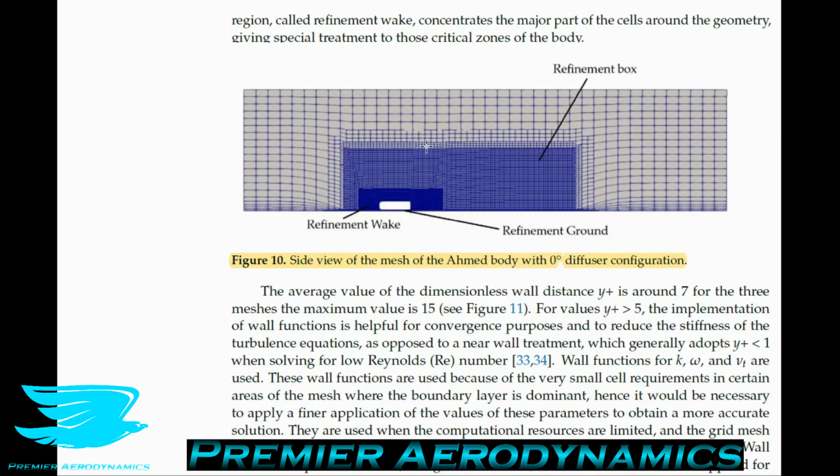Another thing to point out is that going between low resolution and high resolution regions, we have something like a boundary layer, well, I shouldn't say boundary layer because you might get confused with what I mean. It's not a boundary layer, it's a transitional zone between the coarser mesh and the finer mesh. This is just to help reduce discontinuities between these two zones, which could result in divergence in the CFD simulation. So it goes from very coarse to somewhat fine to a little bit finer, and then finally gets to the fine zone at this transition point. You can help your CFD simulation converge nicely and not crash. So that's why they're doing that here.